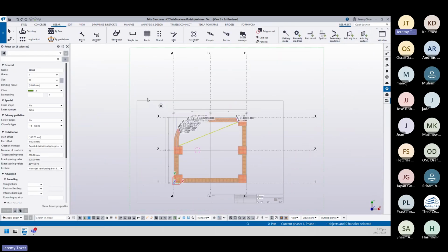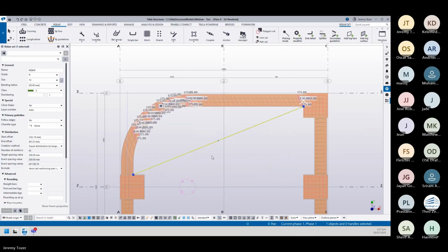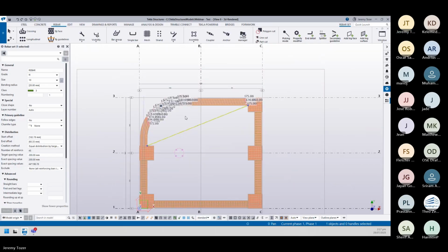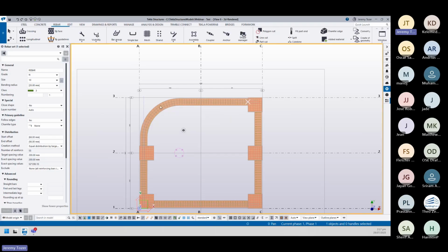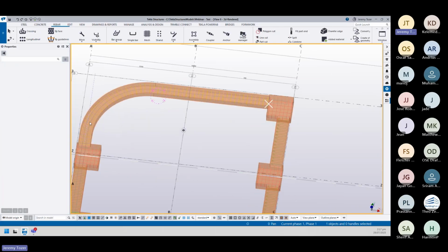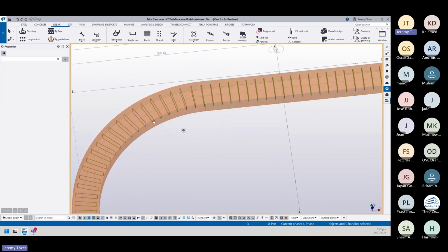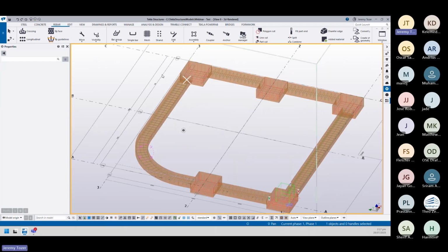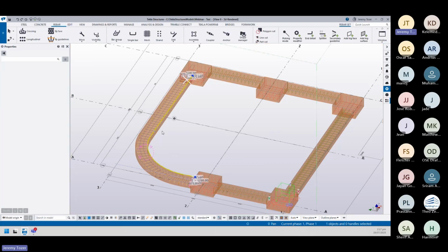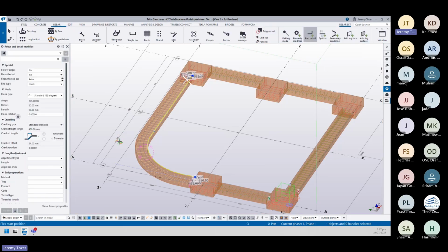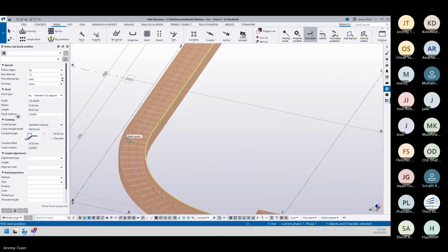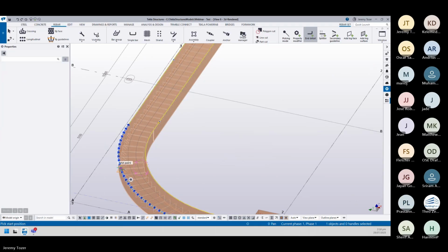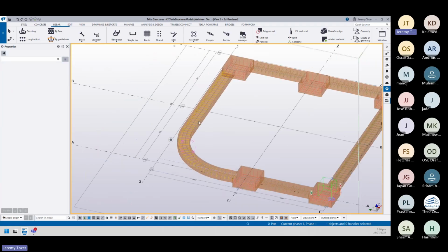Then you select your tools. If you look down on it, you'll see this little context menu here. This button here means follow edges, so you click on that one, and automatically the stirrups have all now followed the curve because that bar has followed that 3-meter radius around. So we can do the same here with the returns. So it remembers what we had and what side we are on, the outside. There we go. And now we've got the returns on all our bars.